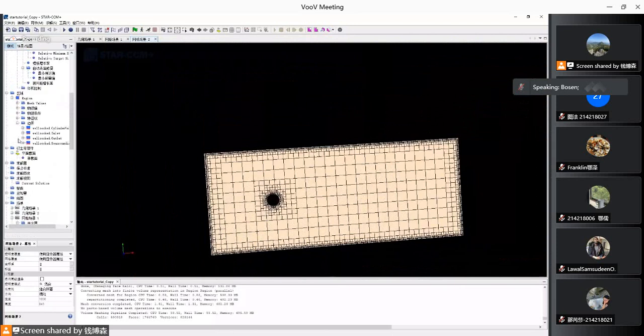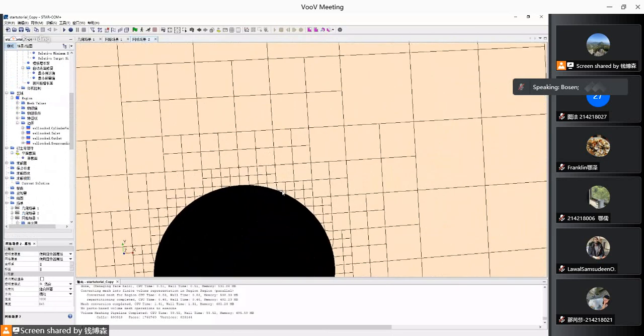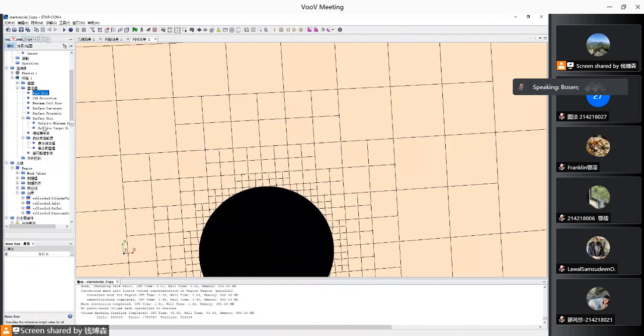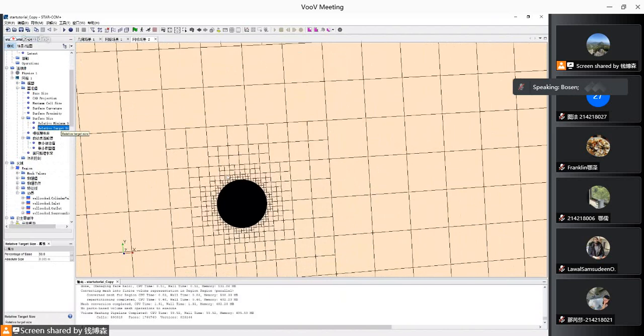Okay, I have put in a very small surface size, which means the size of the surface mesh needs to be at a very small value, such that it can correspond to the volumetric mesh. As I designed in here, the volumetric size is 1 centimeter, but the surface size is 5 millimeter. So that's why there's a growth rate in here.